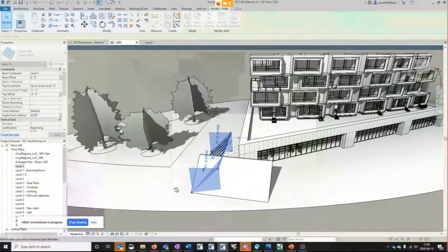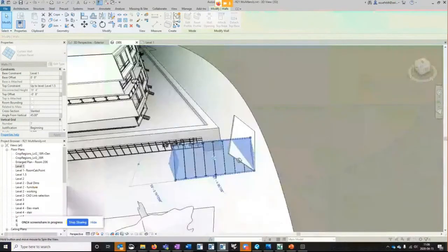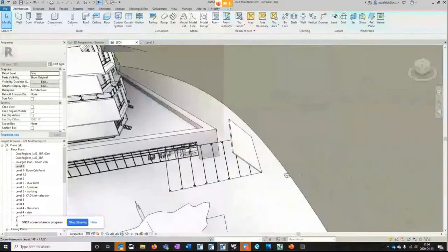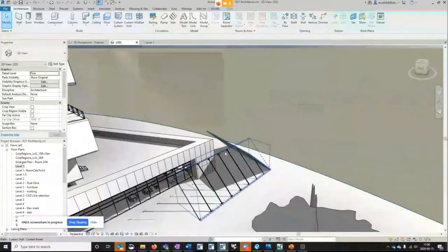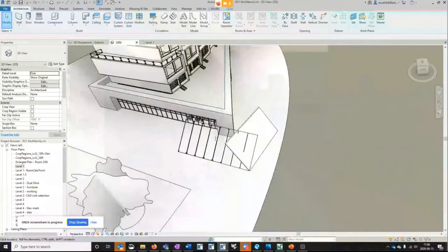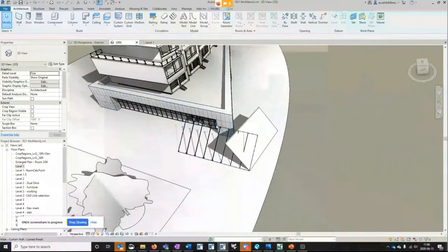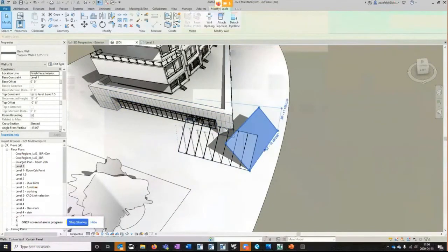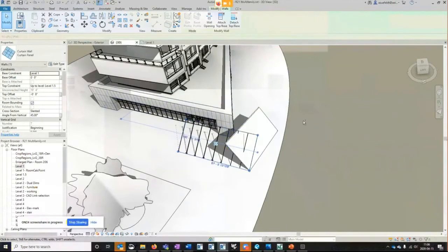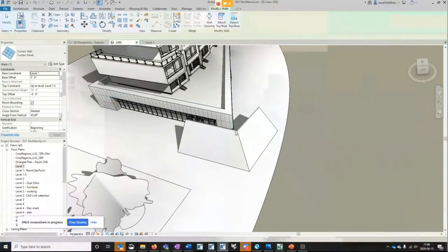Place the panels. All right, and here's a really rough curtain wall, and it's kind of cleaning up. It's not perfect. I would have to take some time to configure this to get everything locked up clean. But just know that it is possible to get these to clean up. And if you check out my blog post I wrote last week, you can see an example where I've got these merging together at a 45 with a solid wall and a curtain wall. Let's go turn that back into a solid wall.